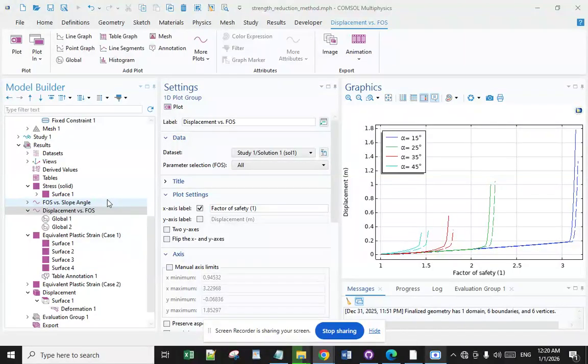The choice of tolerance is also affected by the intended statistical sampling plan and its characteristics, such as the acceptable quality level. This relates to the question of whether tolerances must be extremely rigid, with high confidence in 100% conformance, or whether some small percentage of being out of tolerance may sometimes be acceptable.